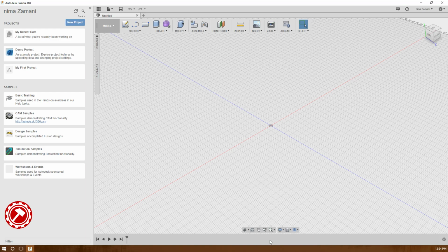So if you want to move some object around, if you want to create a sketch, if you want to create a feature like extrusion, you can see its history on the bottom. And obviously, since it's time-like history, you get the play button and the previous step button, or the beginning button, just like a regular timeline. Let's say if you're watching a movie or something.